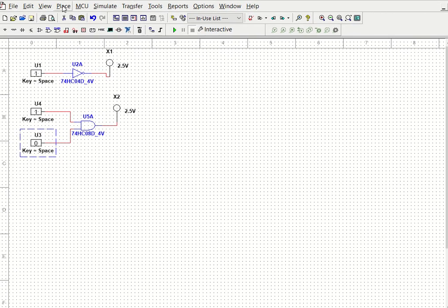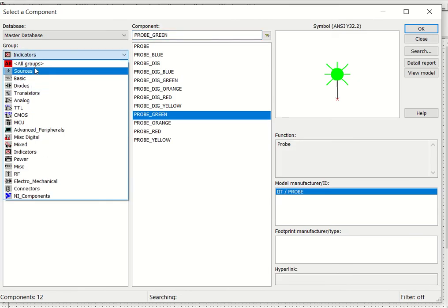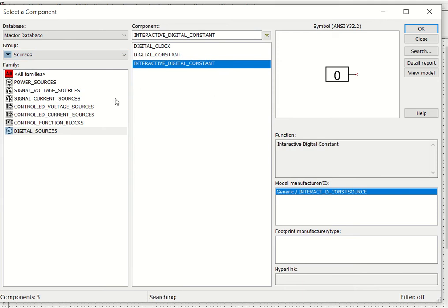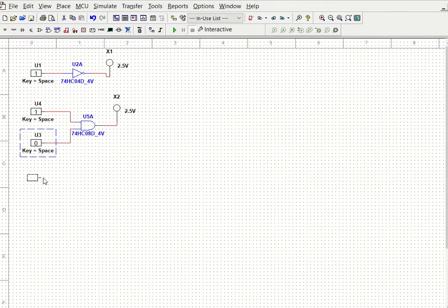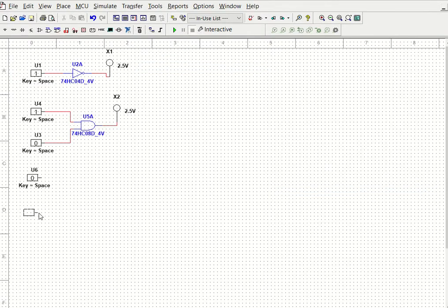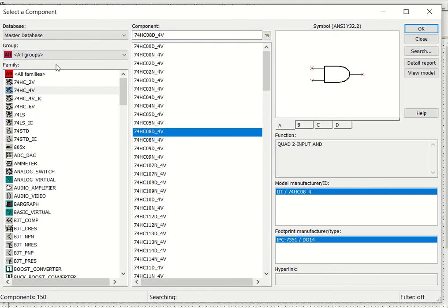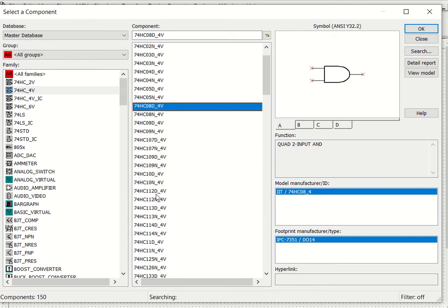So now I would like to show you how to design the next circuit, which was OR gate. Similarly we are going to collect two inputs for our OR gate. Let's say input number 1, input number 2. Next we are going to select our respective logic symbol or logic gate. So for OR, actually we know it is 7432.